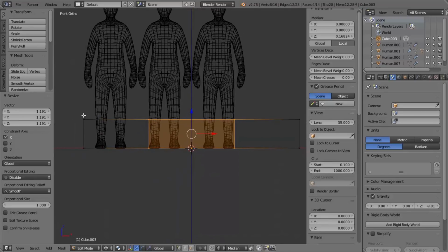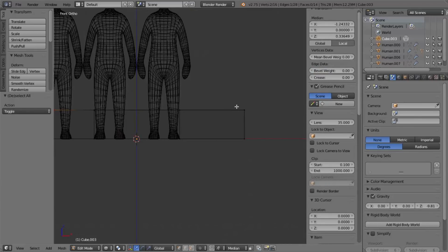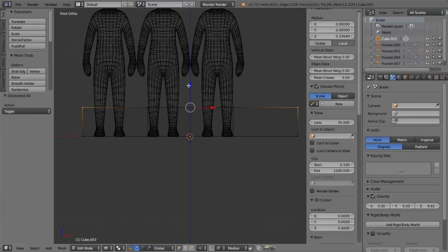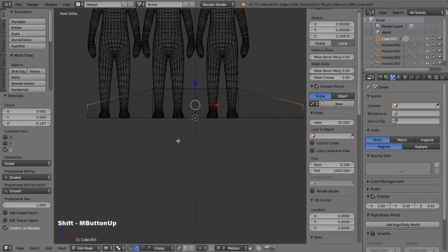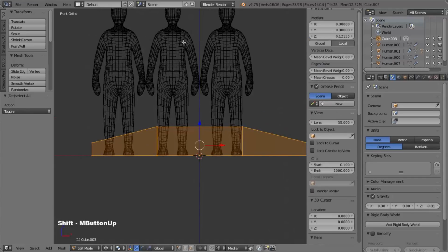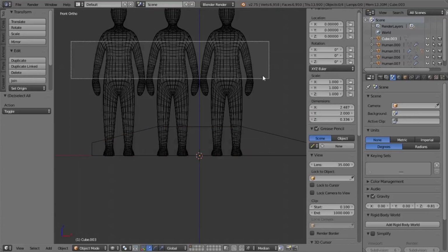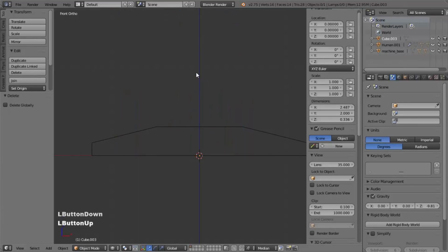Okay, the next thing I want to do is lower these corners. So I'm going to drop my selection and then do 2 box selections around these vertices, and then just lower them down to, let's say, about there. Okay, so now I've got my basic profile shape for the track, and so I don't really need these characters anymore. So I'm going to go into object mode and then drop my selection and then box select those and just delete them.